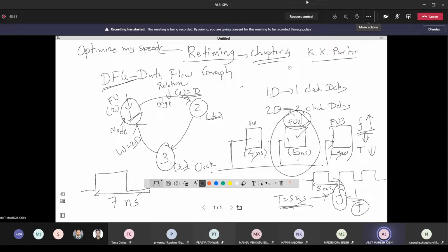But as there is no delay, so what is the understanding? That it has to be complete within this period. Okay, and that has to be one clock period because there is no clock delay. So that means there is no clock delay. So I need to add this and this time, and then I need to think about what should be my minimum period of the clock.